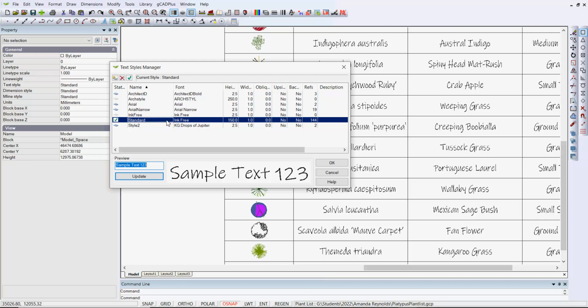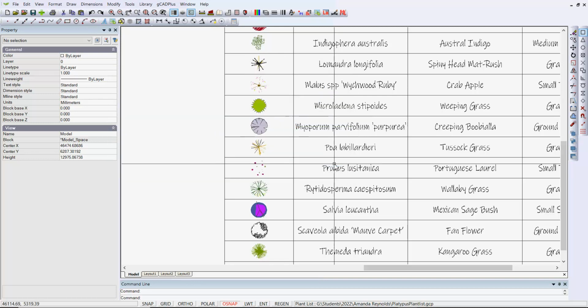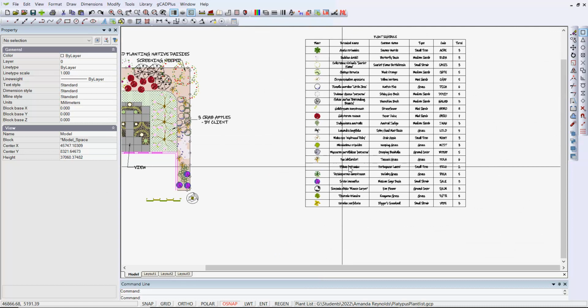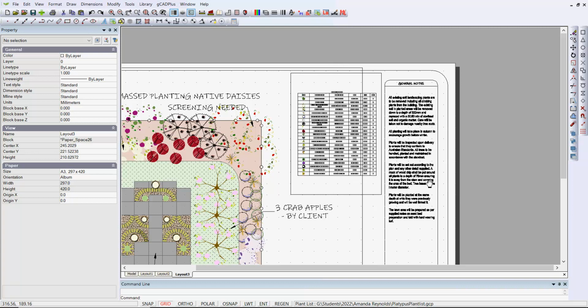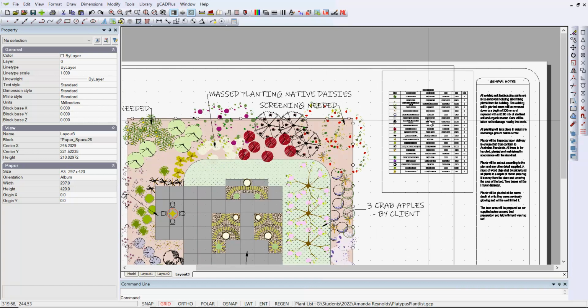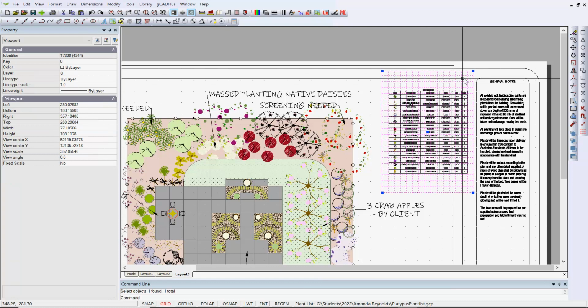So I'm quite happy. That's very quick. But one thing to remember is that you've now set the text style. The schedule is always drawn with the current text style, and we've now changed that definition. So you have to be aware of that. The next piece of text you'll put into the drawing will be drawn using that particular font, because it is set by clicking this green arrow as the current font. So it's a small point, but it can be frustrating to fix.